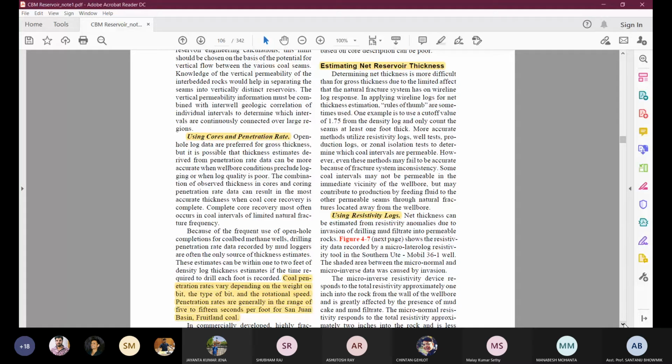Okay, if you see the discussion, they have also mentioned that there are certain parameters which dominate the drill penetration rate: the structure, the borehole position, the drill bit, the type of the coring bit, the rotational speed, the main power of the equipment. There are so many conditions, but from this drill penetration rate, you will be able to get some idea about the strata condition, or the different types of strata.